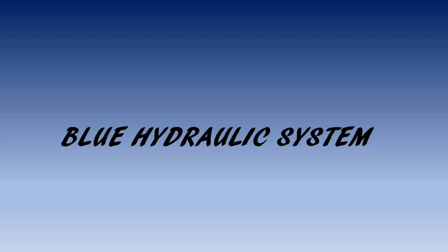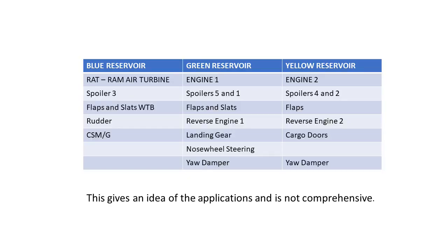And the HP circuit supplies hydraulic pressure to different applications. That would be the left and right spoiler 3, and you can see it on the diagram, all the listings of what it supplies: the ailerons, left and right, your slat wing tip brake, and also the left and right flap wing tip brake, and your elevators and rudder. It also can supply hydraulic pressure or power to the constant speed motor generator. That's another one, and that's only as necessary. Otherwise, it's supplying those user systems.